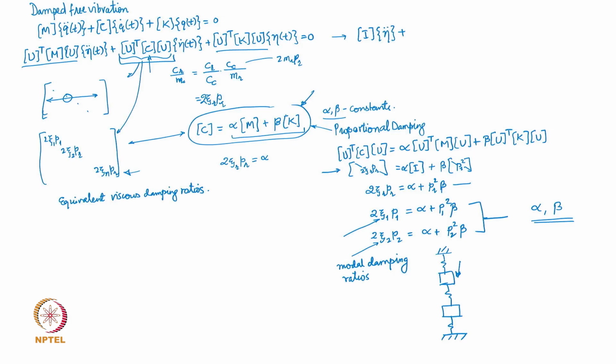You will then obviously get many modes excited, and the time domain data will have contribution from several modes. We have seen that general excitation is not going to excite only one mode. It may excite at least the first few modes quite strongly, and then you can filter this out, get each frequency response, and from that time domain data you can find the damping ratio. You know how to find that using logarithmic decrement.